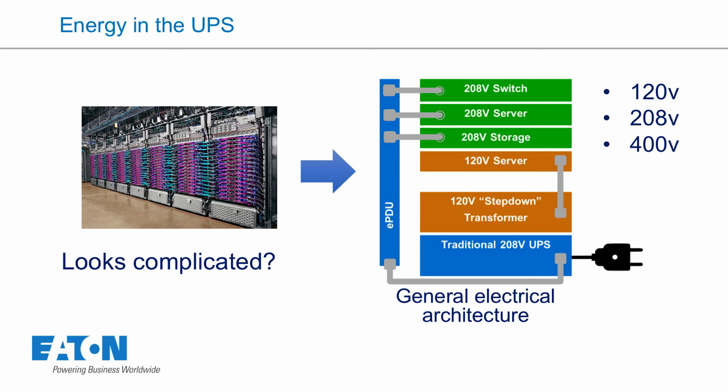Traditionally, it's a single voltage UPS, and an external device is used as a step-down transformer to get, in this scenario, 120 volts. This is typically what you see in a rack. And you see this ePDU, a rack PDU, which provides all the outlet power consumed by the equipment on the rack, backed up by the UPS itself, the uninterruptible power system or power device.